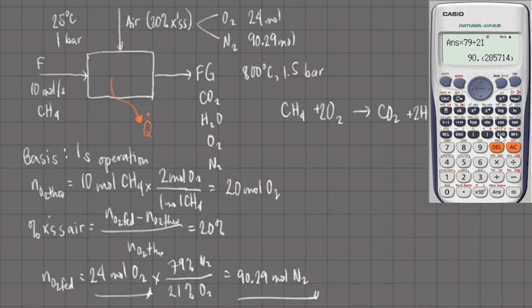This is a common composition of flue gases for material balance calculations involving combustion. Let us denote this as N1, N2, N3, and N4 to facilitate an easy solving of their values. Let us start with N4, or the nitrogen in the flue gas.